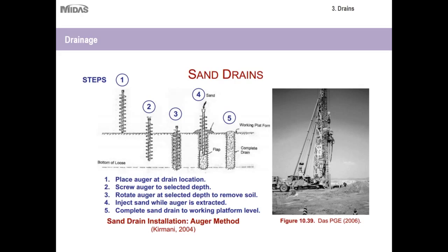So this is something that's very useful. It's proven very useful to increase the rate of settlement and consolidation for clay or saturated clay areas. Typically, when you have an area like this, it's not really safe to build a structure on it right away. Instead, you want to drain the area and then build a structure on it. That way, like I said, settlement and consolidation will be minimized when the structure is actually loaded onto it.